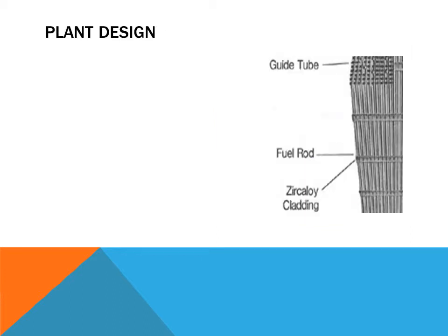Three Mile Island was one of the earlier plants that we put in operation. Not the first, there were others that had been in operation. A little bit about the plant design. It was a pressurized water reactor. Pressurized water reactor just means it had a pressurizer, and it used the pressure on top of the pressurizer to maintain the pressure in the primary plant. This allows you to have high temperature water without boiling.